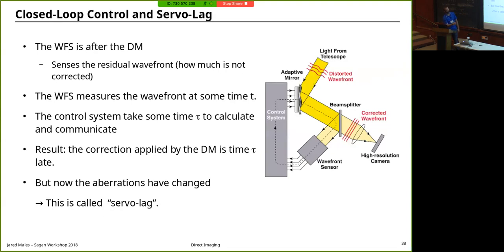This device, which is the deformable mirror, then has to process the signals that came over the network cable, and then it has to move the mirror, which is some massive piece of glass. And by massive, I don't mean big, I just mean it has inertia. So that will take some time to move. So in this whole problem, you're always late. We're always trying to catch up to the atmosphere as it's going by, and we call this servo lag. And even in space, this is a problem, for reasons not having to do with speed so much as the faintness of the stars, of the signals we're detecting, because of the smaller aberrations. But this is one of the key challenges: making the system run fast.